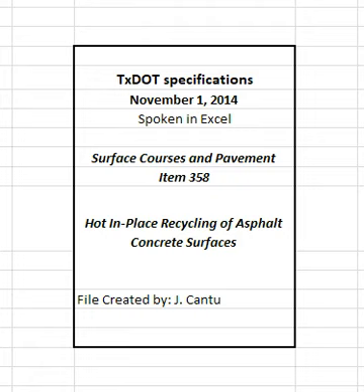Recycling agent will be measured at the applied temperature by the gallon from strap depths measured from the calibrated strap stick for each load or other approved automated means. New HMA will be measured by the ton of composite mix, which includes asphalt, aggregate, and additives. Measure the new HMA on scales in accordance with Item 520, Weighing and Measuring Equipment.